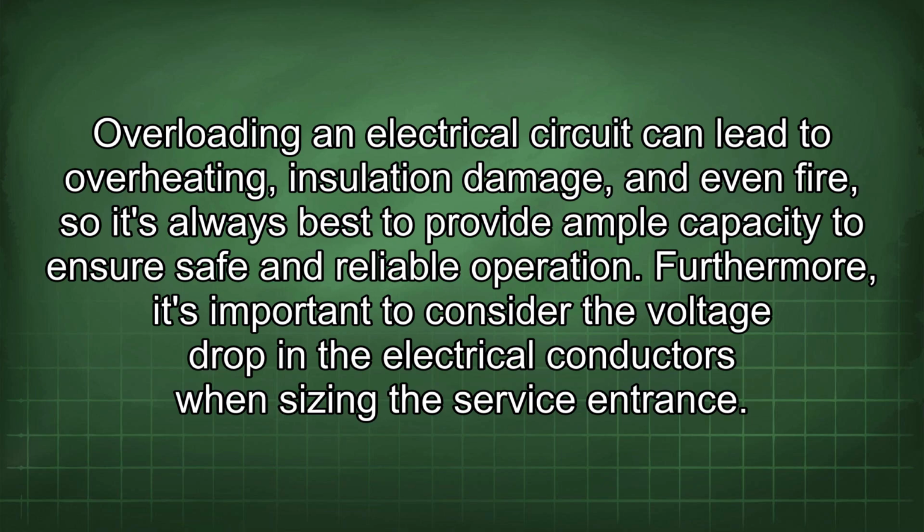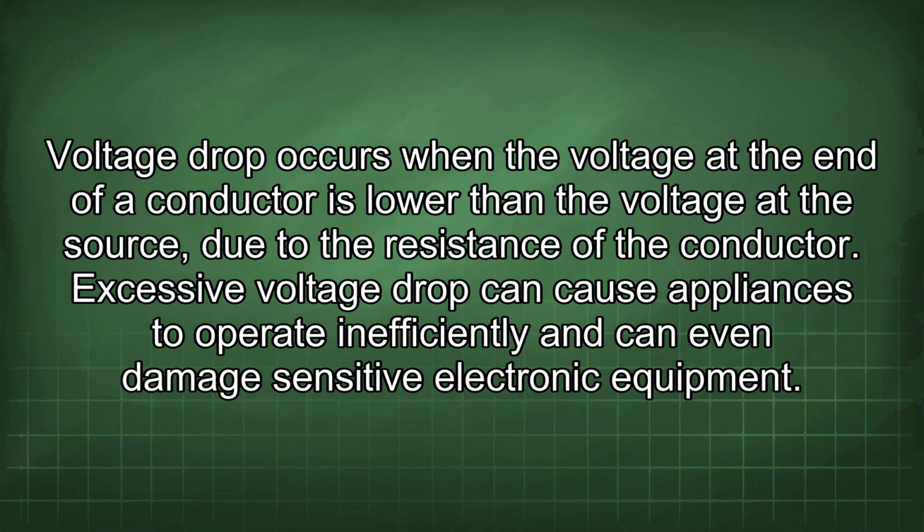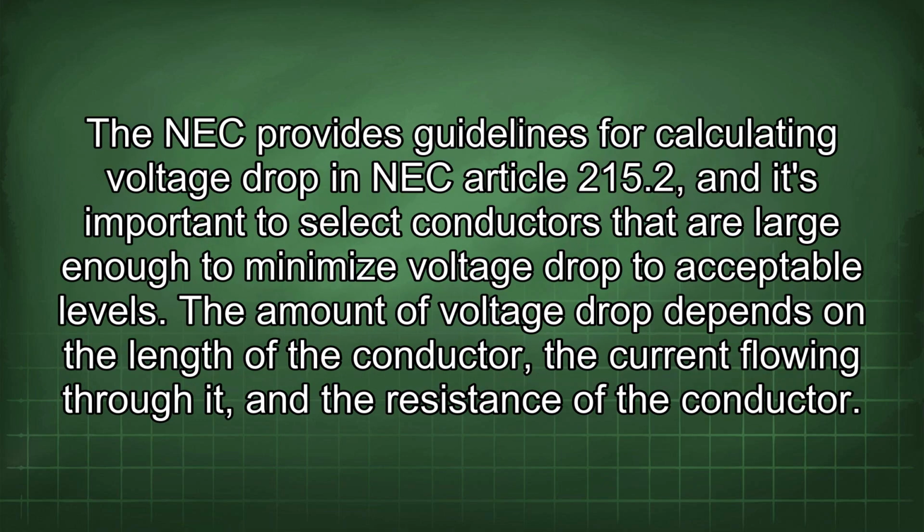Furthermore, it's important to consider the voltage drop in the electrical conductors when sizing the service entrance. Voltage drop occurs when the voltage at the end of a conductor is lower than the voltage at the source due to the resistance of the conductor. Excessive voltage drop can cause appliances to operate inefficiently and can even damage sensitive electronic equipment. The NEC provides guidelines for calculating voltage drop in NEC Article 215.2. And it's important to select conductors that are large enough to minimize voltage drop to acceptable levels.